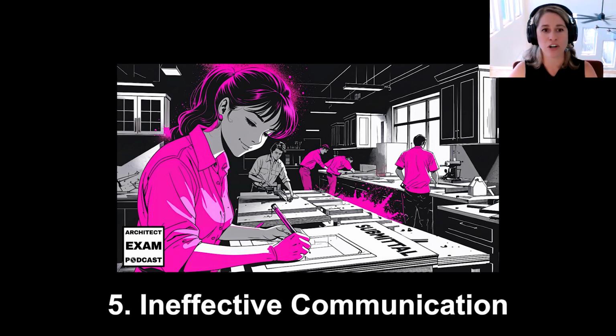process. Another pitfall is just ineffective communication about rejections of submittals and that process, because if and when a submittal is rejected, failing to understand the full reason why before resubmitting can just lead to another rejection of that submittal. So when reviewing a submittal or when receiving a rejected submittal, clarify exactly what needs to change, especially if it's a complex or technical detail component.